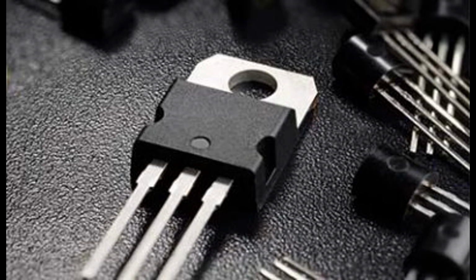7. Capacitances. The operation of a power MOSFET is influenced by its inherent capacitances. Gate-source capacitance, C_GS, affects the gate charging time. Gate-drain capacitance, C_GD, influences the Miller effect, where the gate voltage can rise during switching due to feedback, impacting the turn-off time. Drain-source capacitance, C_DS, affects the drain current behavior.